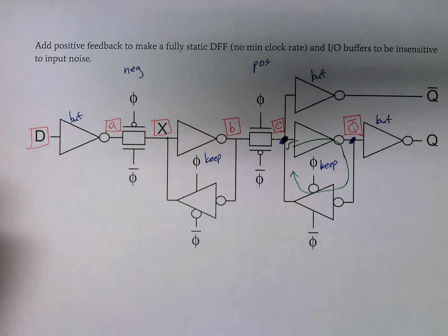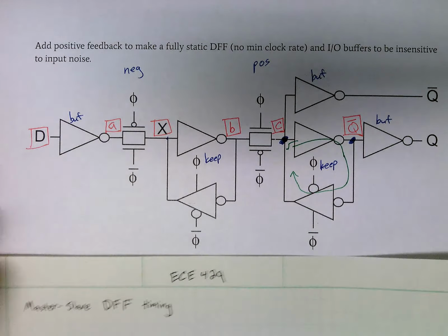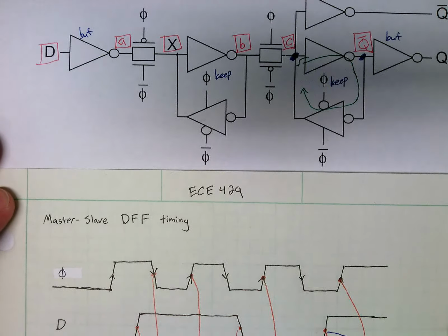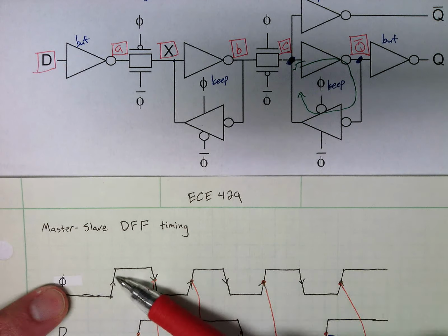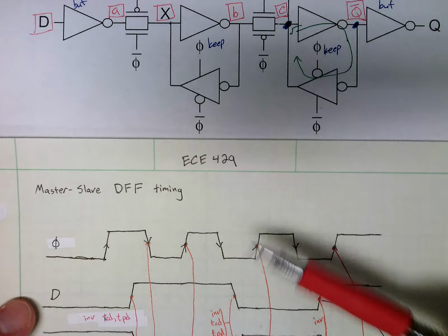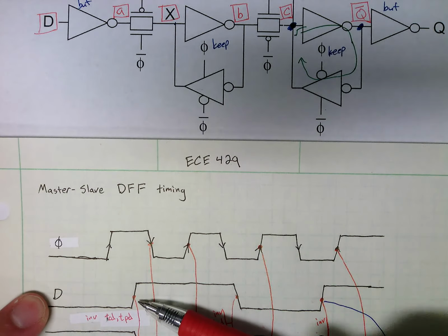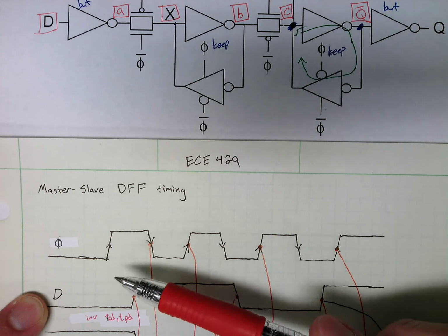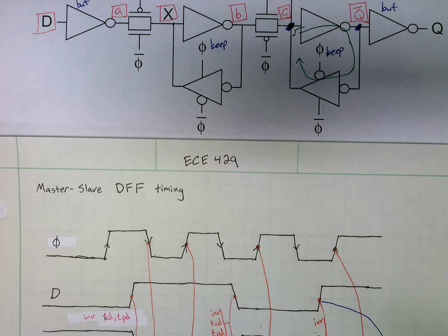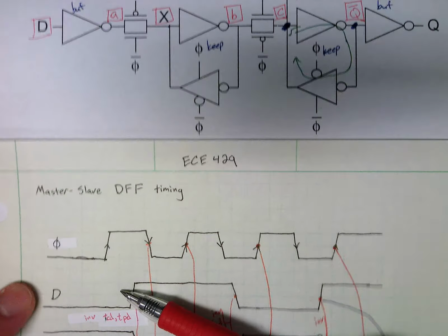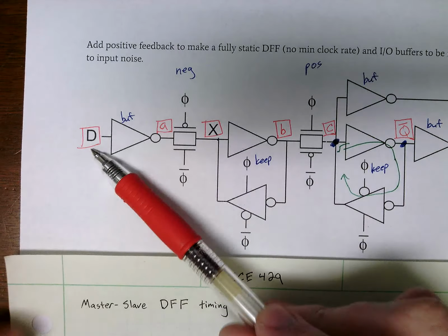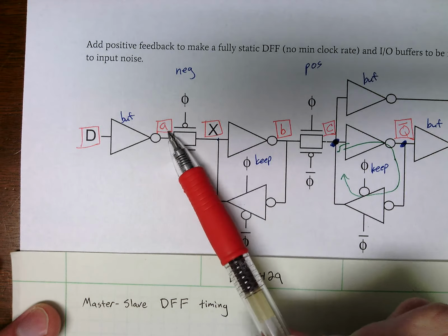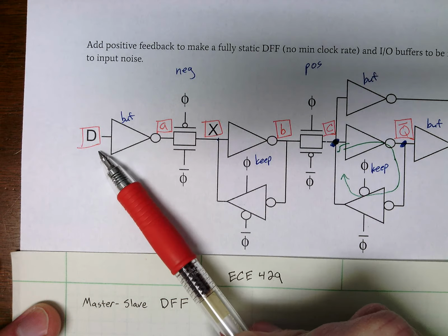What I did is I went ahead and started up a clock signal. All right, so we have a phi signal. Some random waveform for our D. Okay, D is an input. So clock and D are not really necessarily tied together, although we want this to be in a synchronous circuit. We notice that in this circuit A is always the inverted of D, and there's a delay.